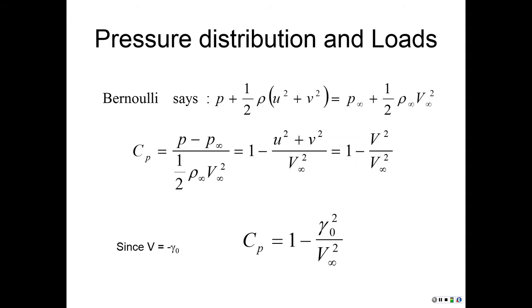You could also do viscous flow, which is a Navier-Stokes solver: ANSYS Fluent, Star CCM, OpenFOAM, software like this, they will compute these. Wind tunnel folks will measure the pressure over atmospheric pressure, which is the gauge pressure, divided by the dynamic pressure. They will compute these. So it doesn't matter how you compute the CP. Once you have the CP, you could integrate it to get the lift and the drag like we talked about in our previous modules.